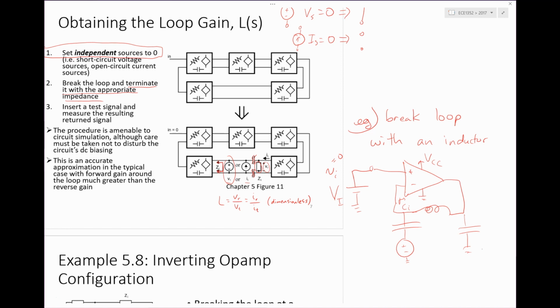Now, some people, if they're trying to be really, really accurate, say that the input capacitance looking into that op-amp terminal will vary if I want to do a different process corner, slow corner, fast corner, or if I want to change the temperature, like the biasing changes or something. In general, the gate capacitance of a transistor may change a little bit. So if you want to analyze what happens to L here in the presence of those kinds of variations, then you need to take that into account, and you have to keep changing this sort of dummy load here, CI. It can be a bit of a pain. So you can either say, well, it's only changing by 10-20%, and anyway, it's a really high frequency pole anyway. That's one kind of approach, right?